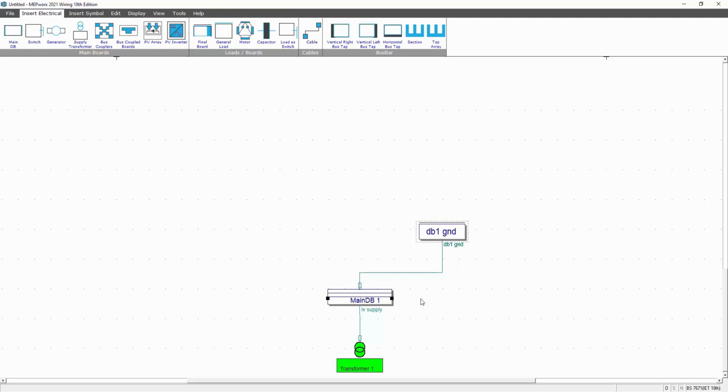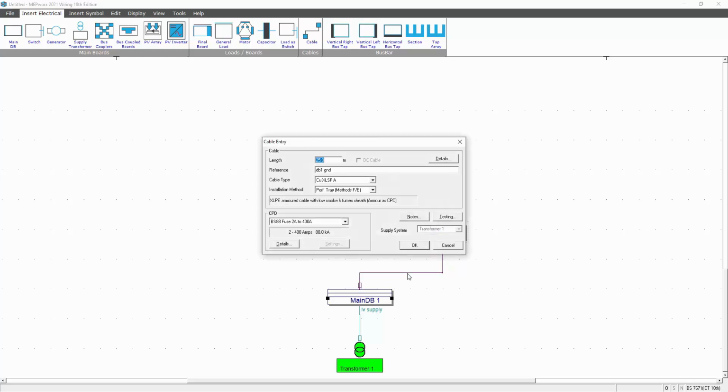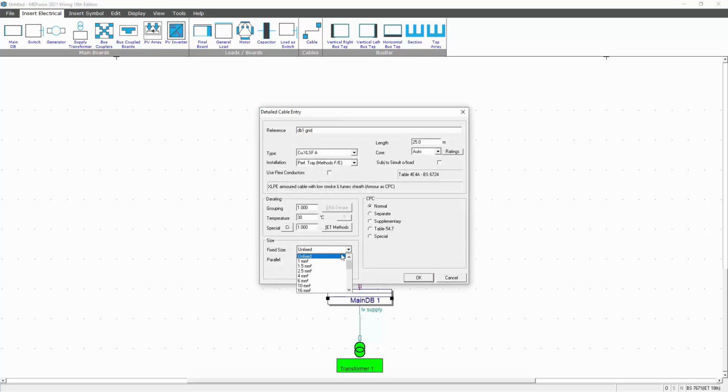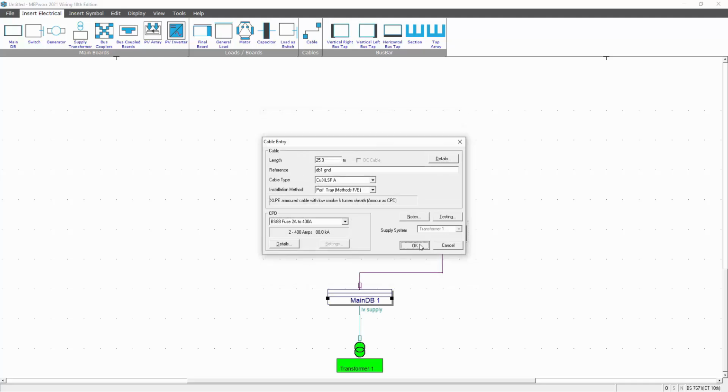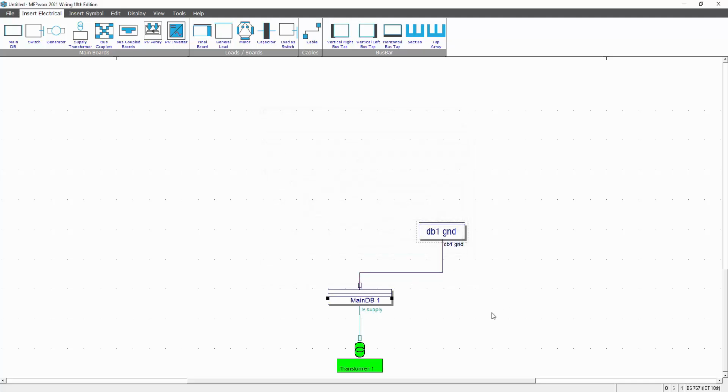There are several cable colours worth noting as well. For example, cyan means it's just a floating cable, it's going to be calculated. If I click on it once, that just happens to mean it's selected. I double click on it and fix anything. So for example, if I go into the details and fix the cable size or fix a breaker or anything like that, that cable is dark blue. Dark blue implies it's fixed.